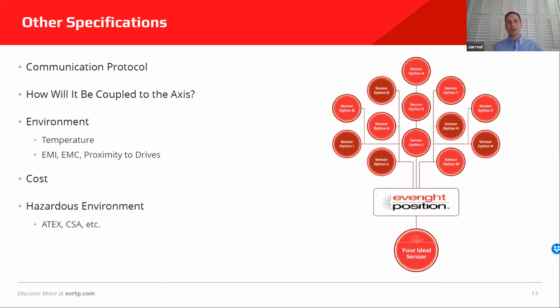Having been on the market the longest, the most options exist with optical encoders. One can find everything from incremental and analog to sine, cosine, CAN bus, Ethernet-based protocols. The list goes on and on. The other technologies each kind of seem to have their own little niche and are most commonly found with industrial standards like SSI and BiSS.